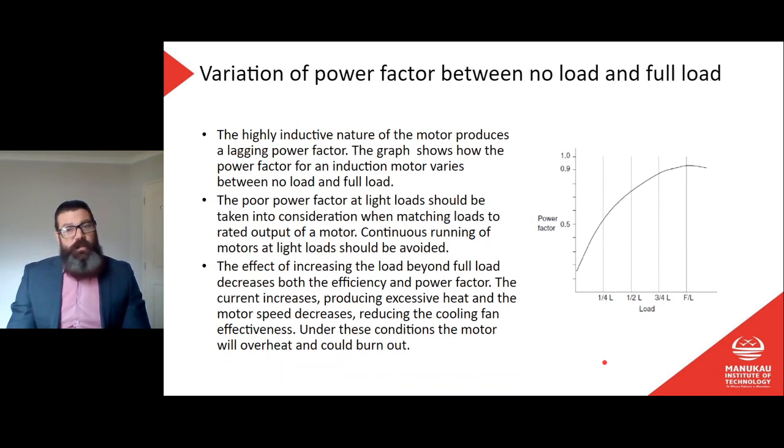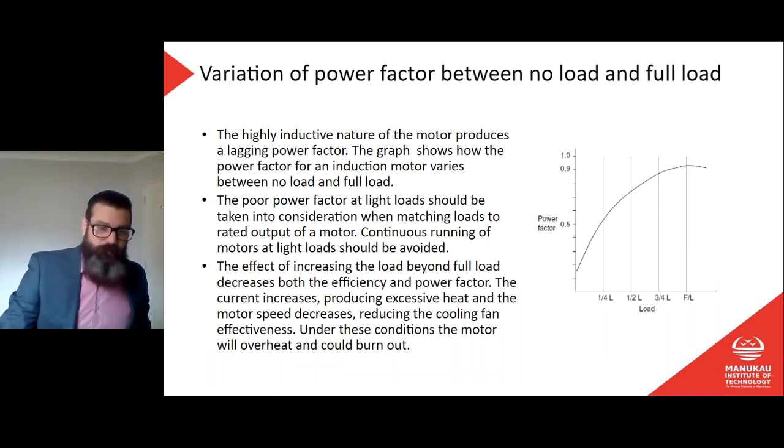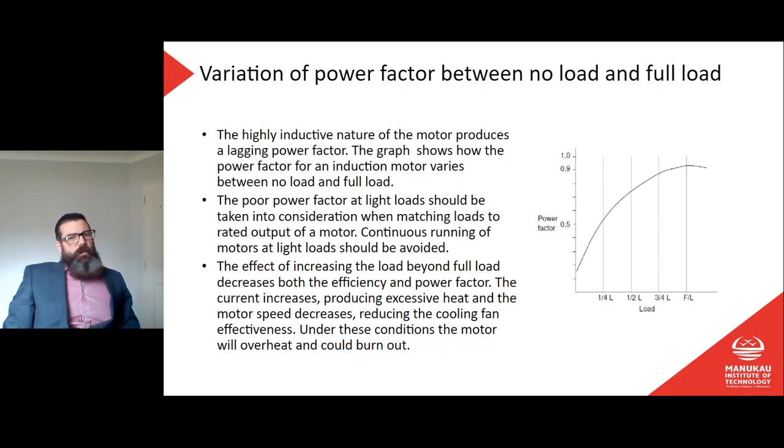Variation of power factor between no load and full load. The highly inductive nature of the motor produces a lagging power factor. The graph shows how the power factor of an induction motor varies between no load and full load. Remember, we know this, right? Every time we create a magnetic field, that inductive reactance causes a lagging power factor. And we can see that there.